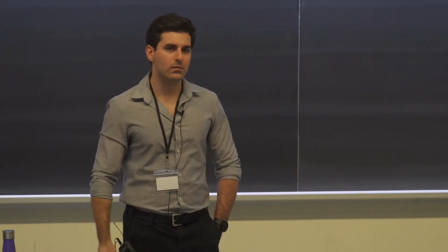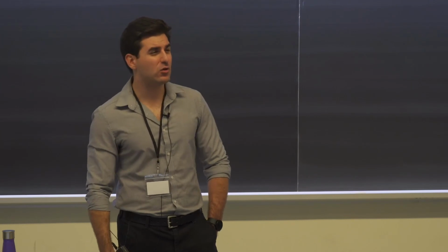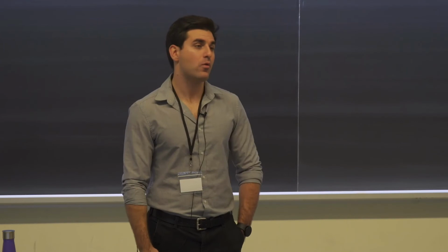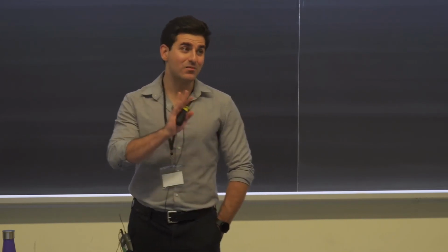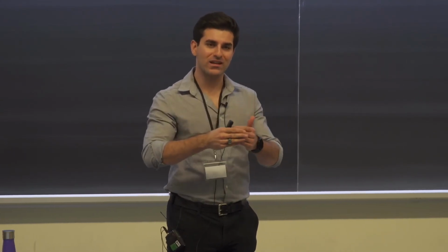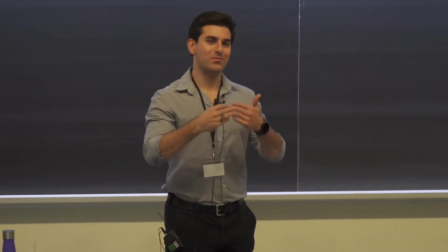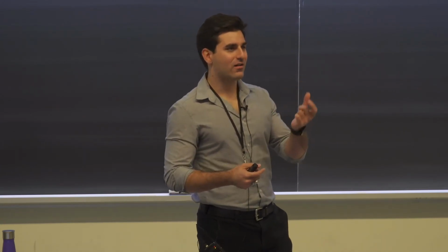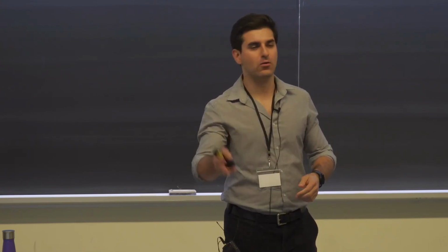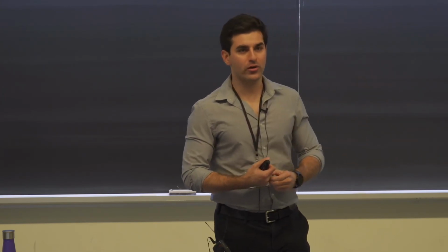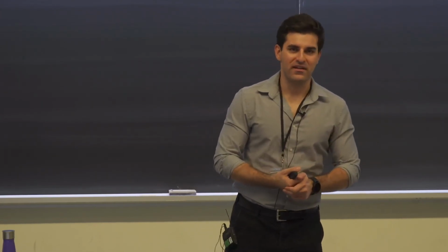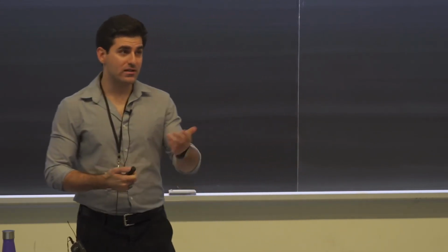And Google just published a paper with a 72 qubit device and tunable couplers that they use to demonstrate break-even for quantum error correction. And that's a big deal, because break-even is the point where, as your quantum error correction code gets larger, your error rate actually gets better. That means the error of each individual part of your error correction circuit, think of it as decoherence or gate errors, is good enough such that as you add more of them, your performance doesn't get worse. So that was on a 72 qubit processor.